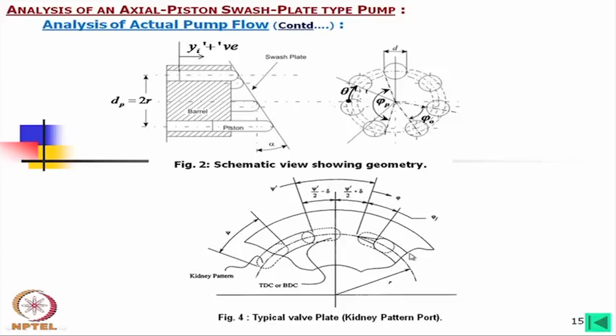Okay. But this needs a dynamic analysis of this pump. From the static analysis we will not be able to understand why this angle should be taken more. If you go for the dynamic analysis and look into the pressure buildup of the oil entrapped inside the piston during this dead zone, we will be able to understand. However, while we are going for the static analysis, still for the opening of the orifice we have to consider these angles.